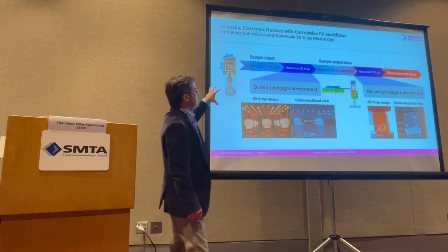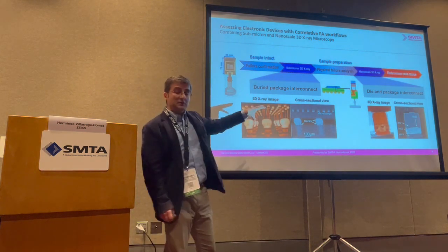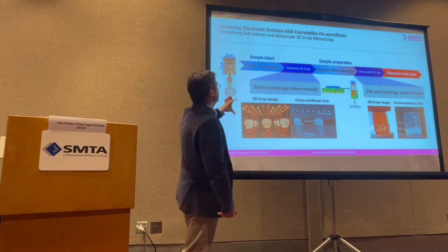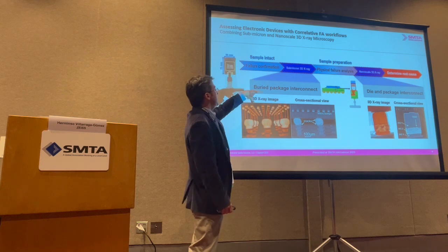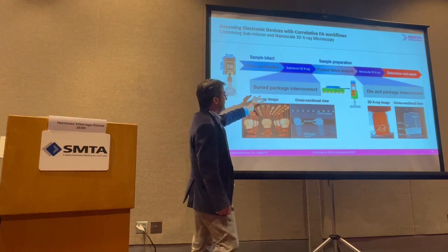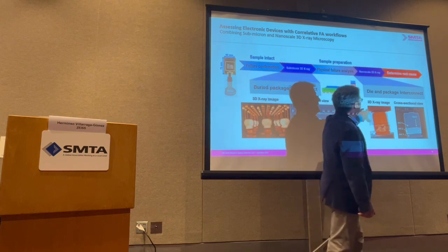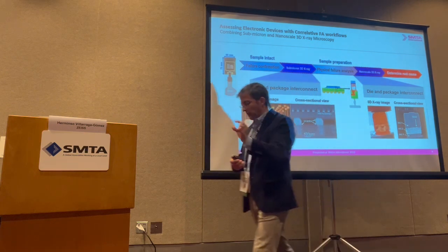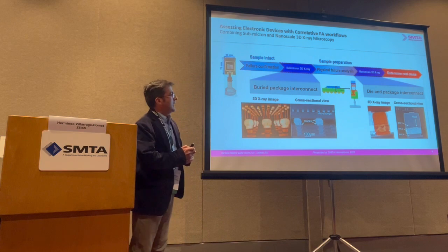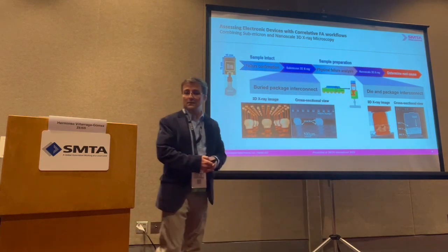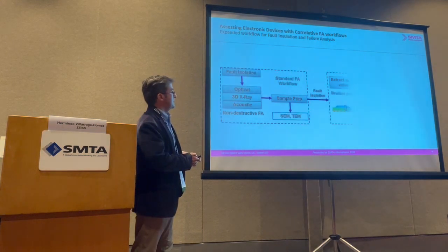So this is a summary of how you can improve the resolution on top of using deep learning algorithms. If you use the traditional submicron 3D X-ray detection, and that's not even enough, you can section a portion of the part and get a small feature that you can scan with a higher image detection that can go down to 50 nanometers spatial resolution.